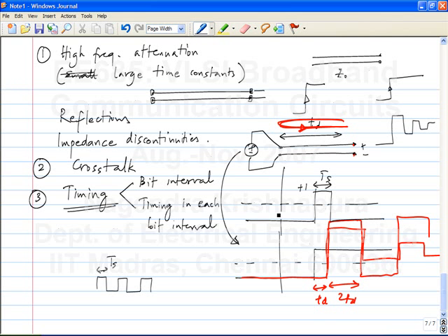Clock skew. Okay, that's a problem, but what's an even lower, that is one of the problems. Meaning, the delay for the clock may not be exactly same as the delay for the data. So even though when you sent it, the clock is at the exact position required, when you receive it, it may not be at the exact position required to receive the signal. Now you have solved the problem of knowing what the bit interval is, right? Because the clock frequency will not change. The bit period will not change. So on the other side, when you receive the clock, you know exactly the interval of the clock and you know exactly the bit interval. But the clock may have got delayed by a different amount compared to data. So that can be a problem.